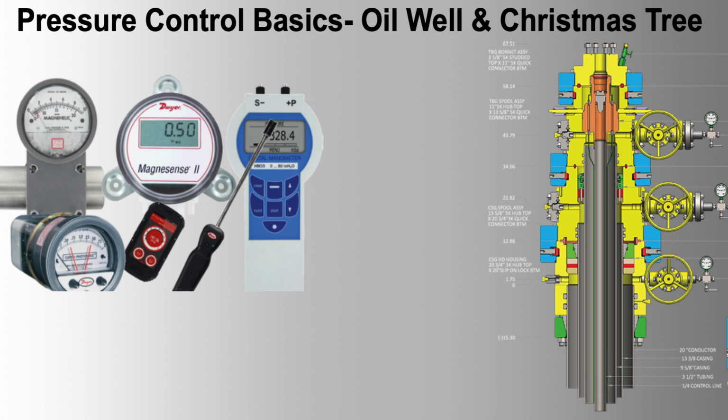Control aspects. 1. Automated control systems. Integration: integrate downhole pressure data with automated control systems to adjust well parameters in real time. Algorithms: use advanced control algorithms to predict and respond to pressure changes promptly. Example issue 5. Overpressure events during production.